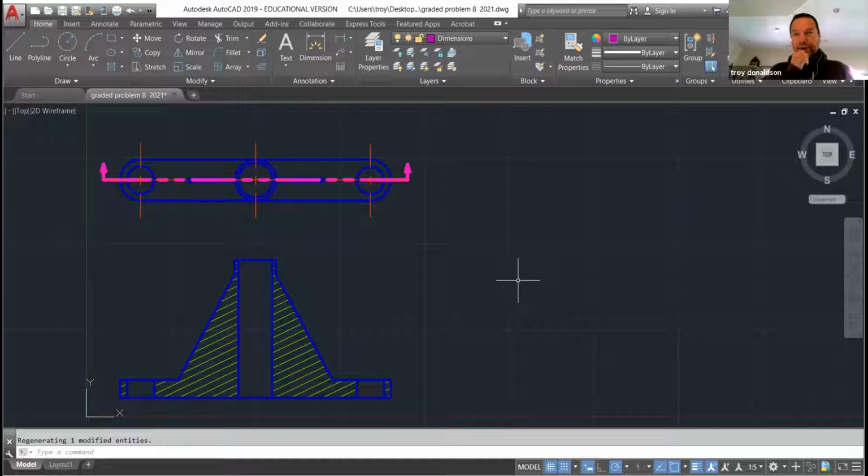So kind of first thing, you're going to need an organizational system to save these things. There's two different kinds of blocks. There's a block, and that's just going to be within the drawing. And then there's a write block, a W block. I always make W blocks, then I can use them in other places. Now, you can use a regular block in another drawing. You just have to go steal it from that drawing. Okay, so it's a little more difficult.